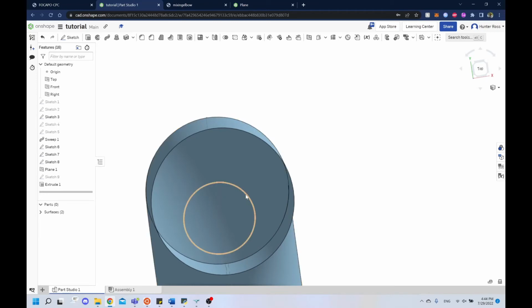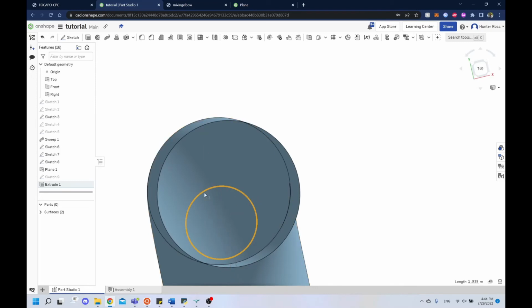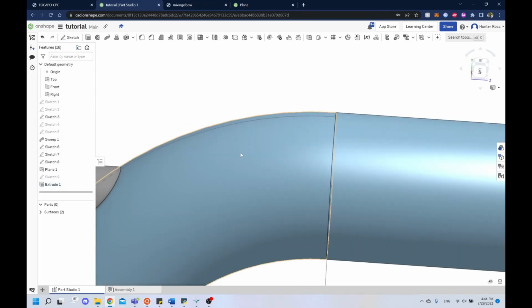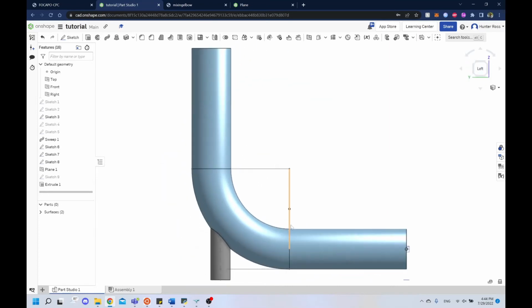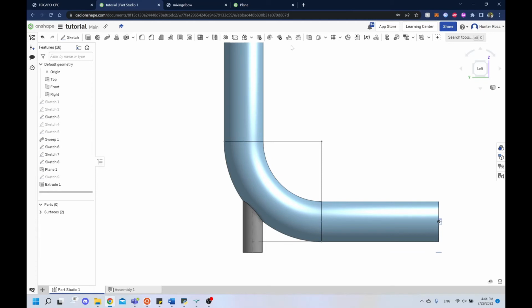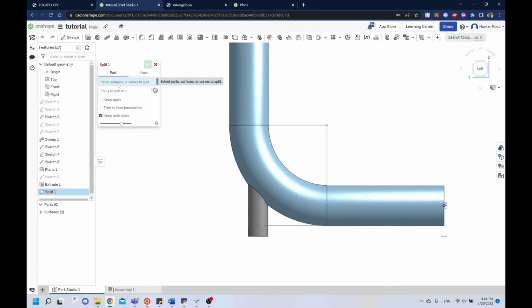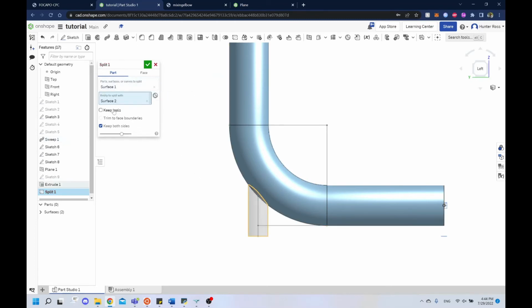So there's two ways we can go about that. Because it created a new face here, it looks like, and we can actually delete that face. I'm going to show you both ways that I could think of to fix this. One is something called splitting. We can split, say, okay, the part that we want to split is this face here. Split it with this entity, and this entity is considered the tool that you're splitting it with. Imagine we're cutting into this face with this small section of elbow, and we're going to want to keep that because this tool is actually relevant.